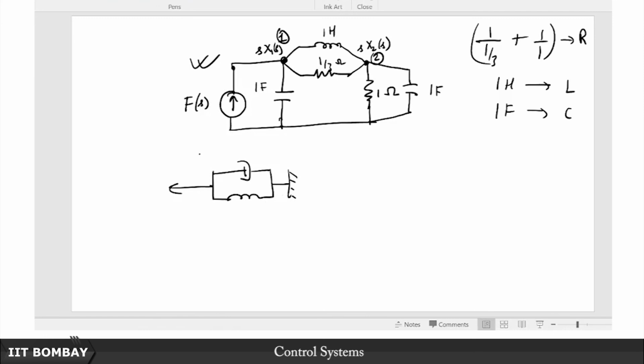So you know that the overall displacement of this dashpot and the spring is identical, isn't it. So this is x. You can clearly write that if F is the force that is applied, then F is equal to nothing but Bx dot plus Kx. So this is when they are put in parallel.